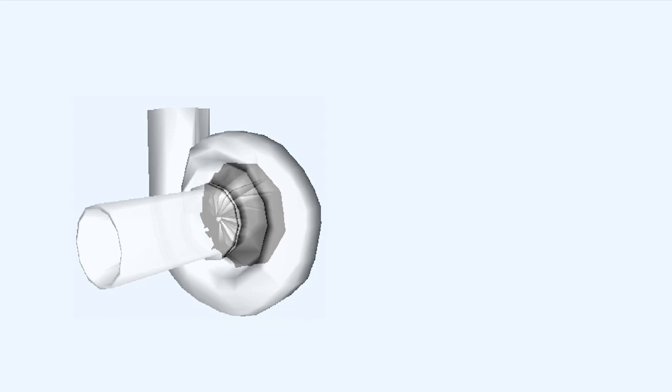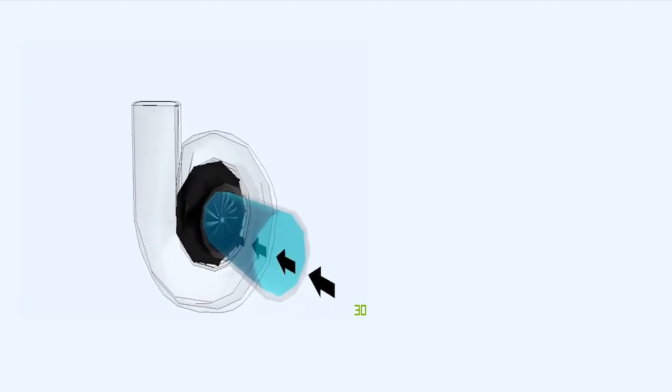As we stated previously, the most commonly used compressors are the centrifugal type. Centrifugal compressors are comparatively light, able to run at high speed, will handle large quantities of air, and are both robust and reliable. A centrifugal compressor consists of two components: the impeller, which is rotated and accelerates the air, and the diffuser, which collects and directs the air into the inlet manifold.